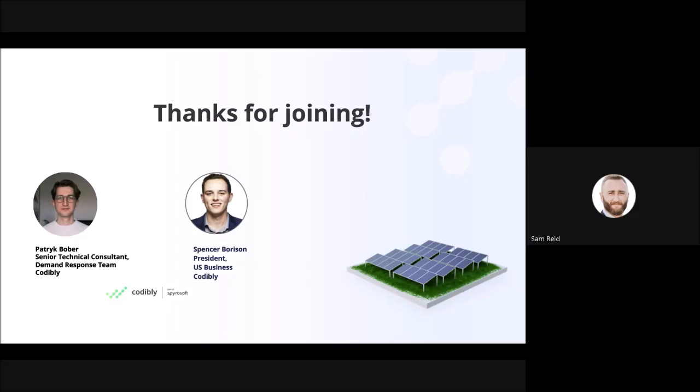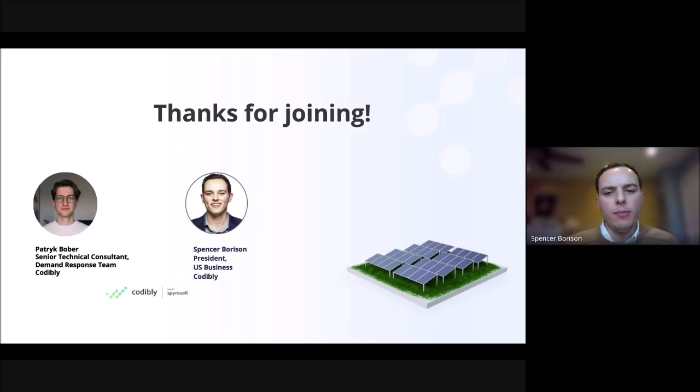Other than solar inverters, are there any DER device OEMs in the U.S. supporting IEEE 2030.5 instead of their proprietary APIs at scale? Yeah, I'm happy to start with this one, and then SunSpec, I'd also be curious about your thoughts on this one. I would say from what we're seeing, 2030.5 is still the most established with inverter use cases, certainly, especially around California Rule 21 and some other programs that we mentioned. There is certainly heavy reliance on proprietary cloud APIs for some of the other device types, but I will say that we've seen some emerging use cases.